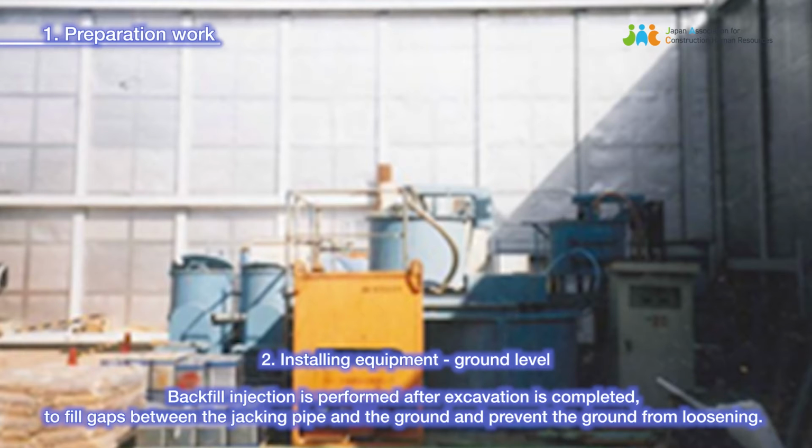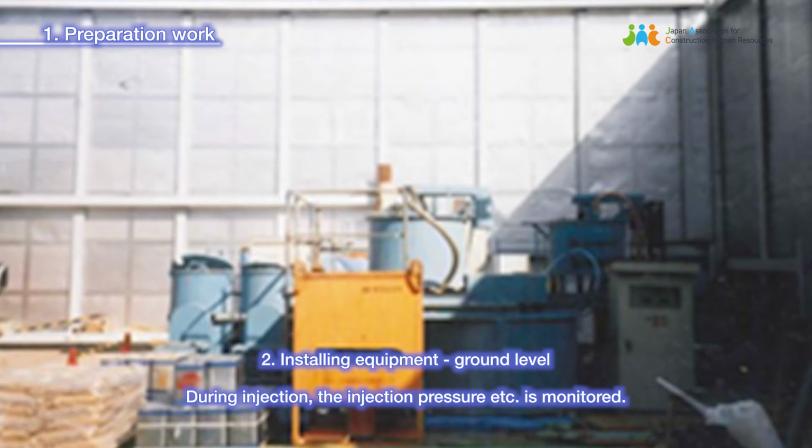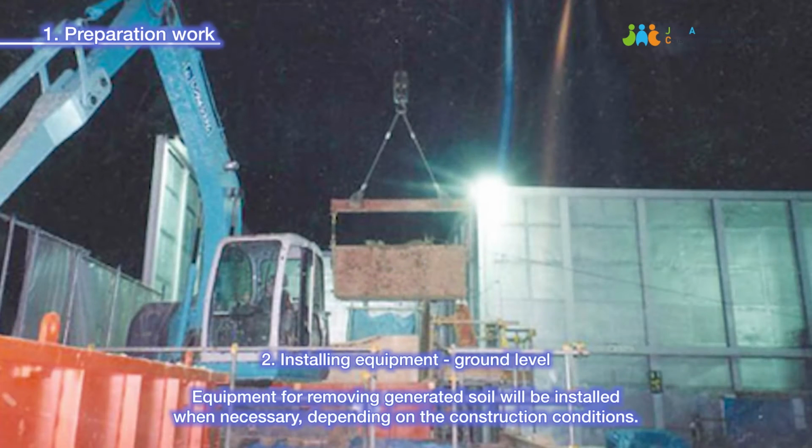Backfill injection is performed after excavation is completed, to fill gaps between the jacking pipe and the ground and prevent the ground from loosening. The backfill made by the injection equipment is pumped into the tunnel pipe through piping, and then injected through the grout holes of the pipe. During injection, the injection pressure etc. is monitored. Equipment for removing generated soil will be installed when necessary, depending on the construction conditions.